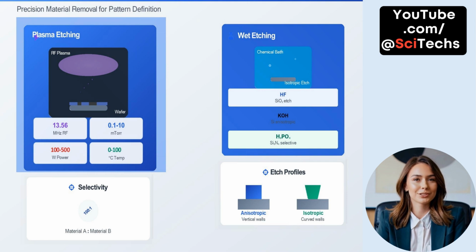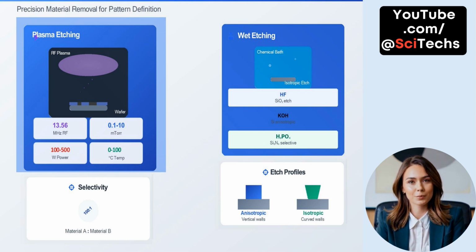Wet etching uses liquid chemicals in a bath. Hydrofluoric acid, HF, is used for etching silicon dioxide, potassium hydroxide, KOH, for anisotropic etching of silicon, and phosphoric acid, H3PO4, for selectively etching silicon nitride. Wet etching typically results in isotropic profiles, with curved or undercut sidewalls, while plasma etching supports anisotropic vertical profiles.